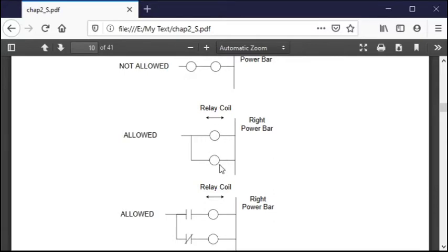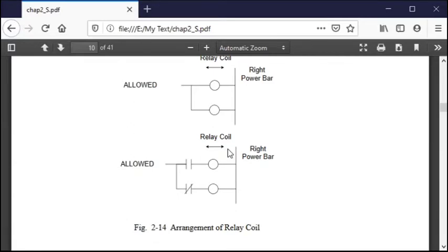And that's actually happened in the past, where I'd be programming along and I have it named a certain way, and the guy that was doing the HMI panels thought he'd better put a different name. I come back the next day and there'd be another coil sitting there, and he had it named his way. So again, you can settle a lot of arguments if you say, well, you just put another coil there and let it go. But that's the only reason I can think of that in a programmable controller you would have 2 coils sitting there doing the exact same function.